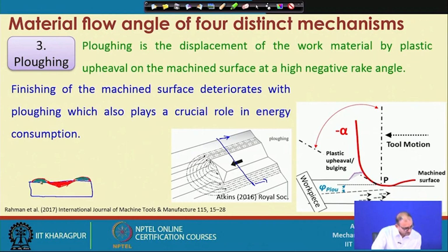Right. So, this and this material, right. Now, this part is okay. Now, let us see that your tool is moving to the next location. Now, this part is over and our depth of cut is this much. Consider this is the depth of cut, and now we want to remove some material from here. So, again see how much amount of material we are removing from here. So, if you calculate this area, just a minute.